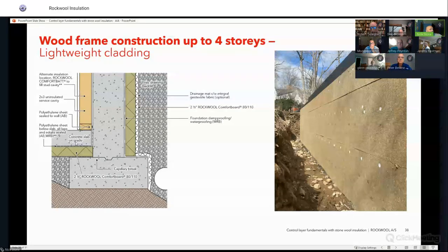If you wanted to go below your slab, you want to go insulation, vapor barrier, and then concrete on top of that. It's really important to have that sequence for a drying standpoint, and also it would just keep that drainage capability always draining, and that's what we want for the Rockwool products.